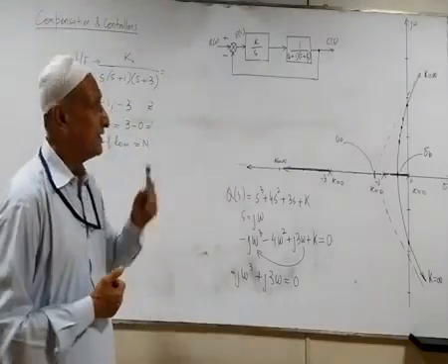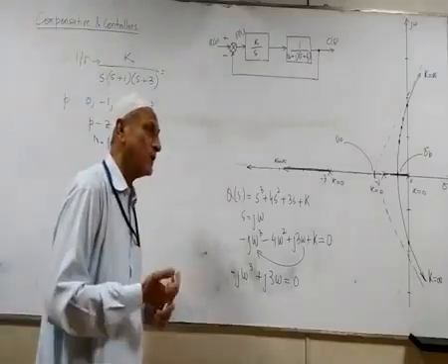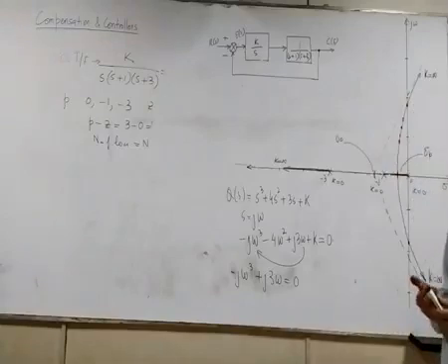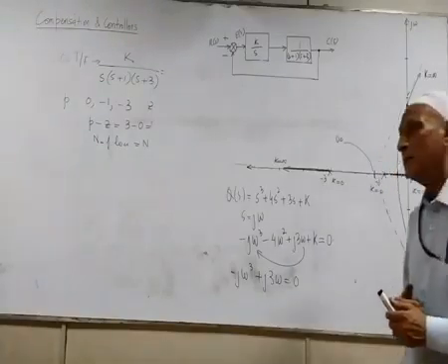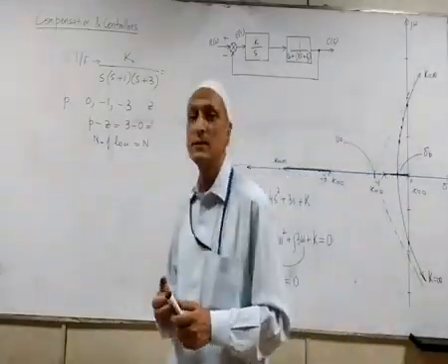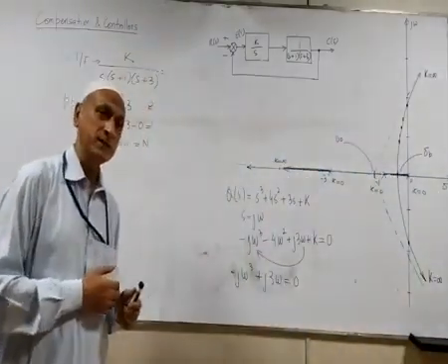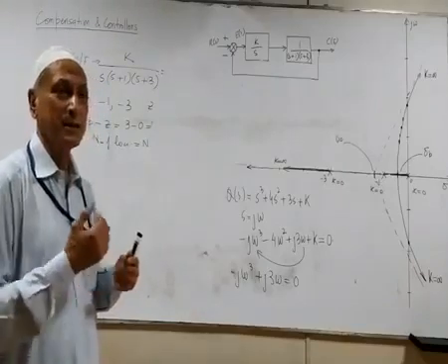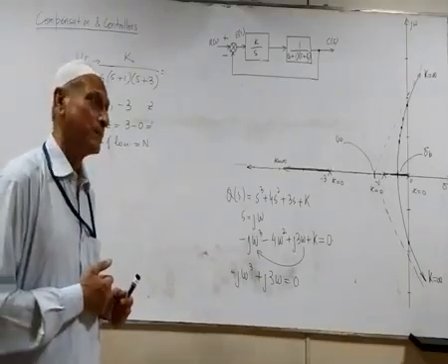Now, on the other hand, when you incorporate an integral controller, a simple gain integral controller of the form K over S, then you are actually deteriorating the transient behavior of the system in terms of a slower acting system in getting rid of the disturbances.